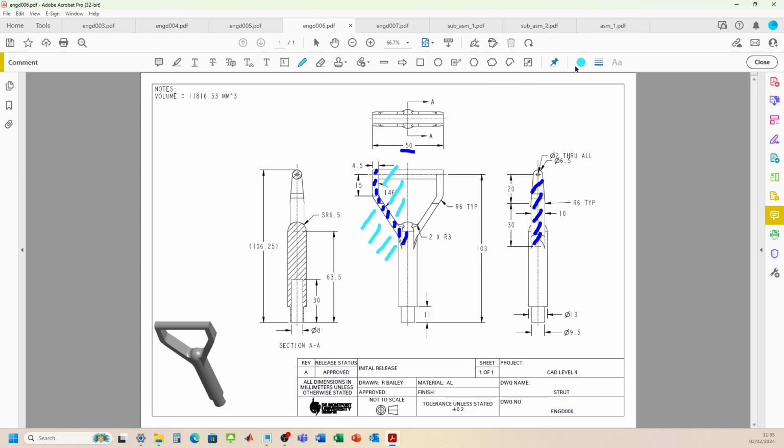Let's go back to my pen. So the next step, once you've got that shape, you'll then add in the circle there. We know that the diameter for that is 6.5, and then we can just extrude that in again the required amount so that it fills in this central section. Okay, so once we've worried about this top section, we can then start to think about the bottom.